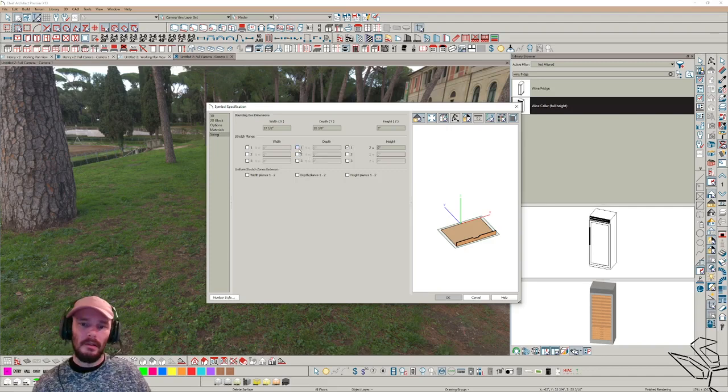That one's fine. Our depth plane, we could bump this up to 10 inches, something like that. Or negative 10 inches, excuse me. And then our width plane can leave on 0. Actually, no, I don't want to leave that on 0, because this is going to get resized across the width, right? So we could copy this here, paste it here, divide by 3. What do we get? There we go, perfect, right? Copy that, paste it here, negative. Perfect, stretch planes, done.